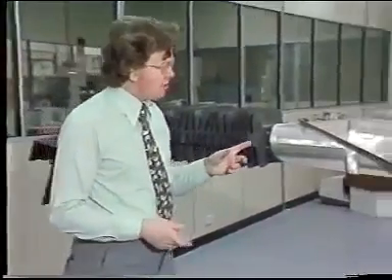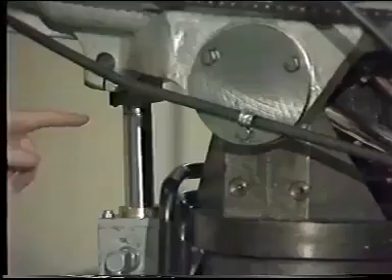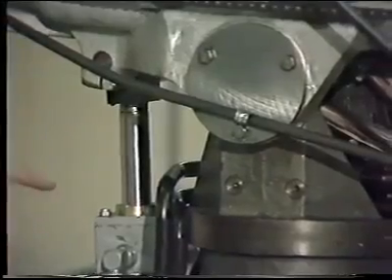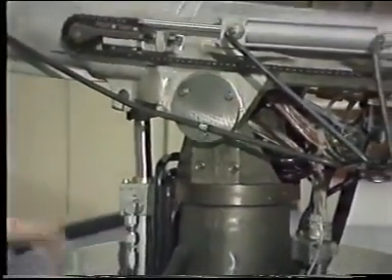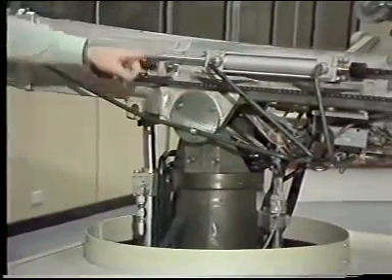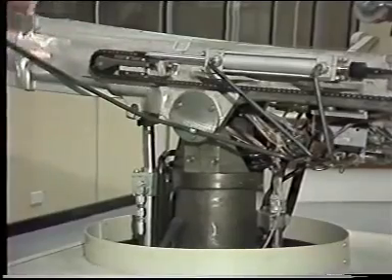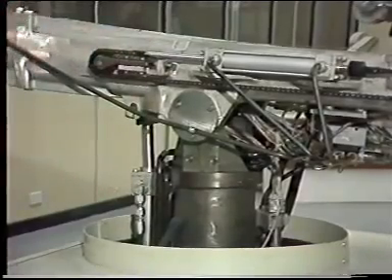And then further up, we've got another difference. We've got a vertical link here with a prismatic joint. That's connected by a horizontal link inside here. There's the main vertical link and the horizontal link across the top, making a complete loop of links and joints that we didn't have on Puma. So we've not only got different types of joints, we've also got them connected together in a different kind of way. And that raises an interesting general question. If I know what type of links and joints I want, how can I connect them together and still be sure that I've got the right number of degrees of freedom back here at the end?